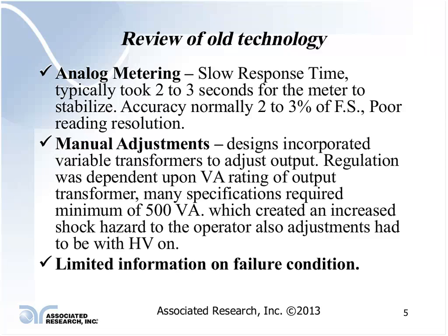Okay. Limited information on a failure condition. Again, older testers had, in many cases, maybe just a kilovolt meter. You might have had a leakage and a breakdown light that lit up to indicate a failure. Some units had current meters, some did not.